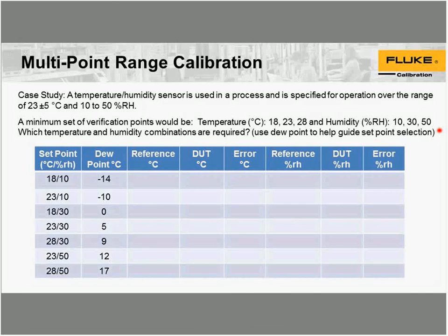Okay. Another question, Mike. I don't know that we addressed it for sure. We kind of alluded to it, but can you use a chilled mirror with the Fluke 5128 to improve its accuracy? And then would that be close to a two-pressure system if you did that? Absolutely. You can use a reference chilled mirror with it to improve the uncertainties.